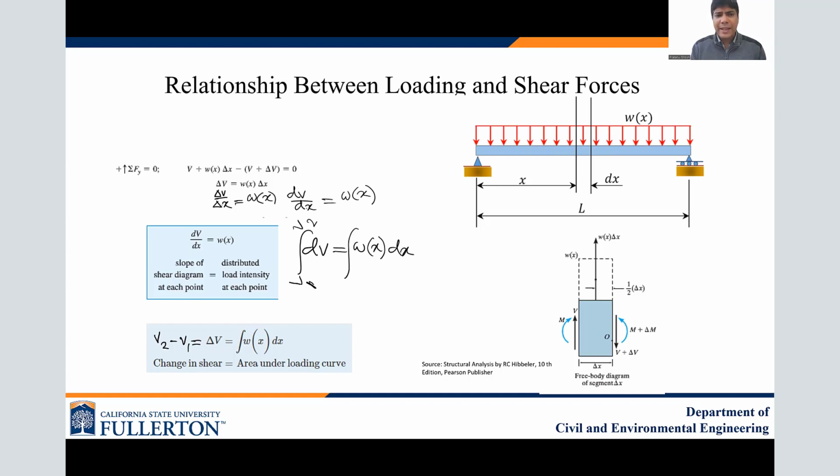Being said that, we can imagine that from math, we know dV over dx is the slope of the shear diagram, basically, and it will be equal to the distributed load intensity at each point. So this gives us a clear relationship between external distributed loading and shear forces.